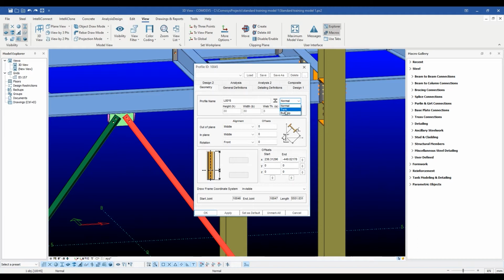A twin section, on the other hand, is a section in which a particular section is used either twice or 4 times as a single entity. So, for instance, back-to-back angles, cross angles, back-to-back channels, face-to-face channels, etc., all fall in this category.